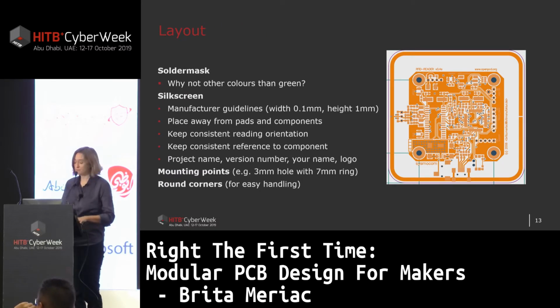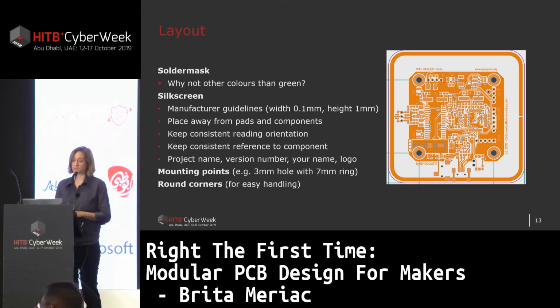So the solder mask covers the copper tracks and leaves some clearance to the solder pads. It's usually green, and thus it's the cheapest choice. For prototypes or hand soldering projects, it's definitely a good choice because our eyes are sensitive to green. But there are lots of other colors available, and a pure white board or black board definitely looks cooler than a green one.